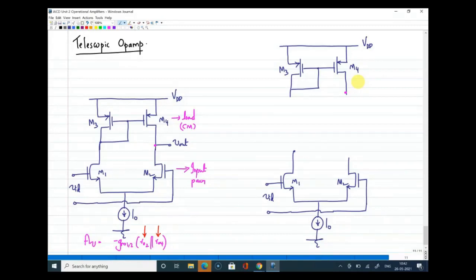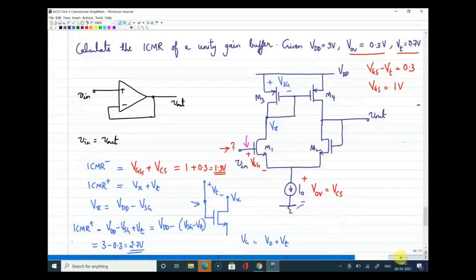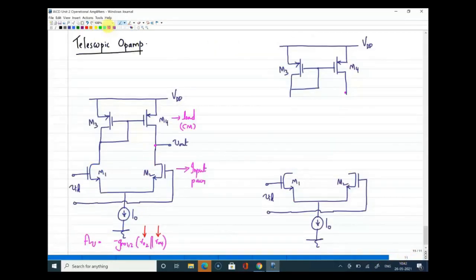So you have devices M1 and M2. The very first thing we will do here is add cascode transistors for M1 and M2. So listen very carefully. How will I add? I will add in this form. Since it is cascoding, I will use the same device.